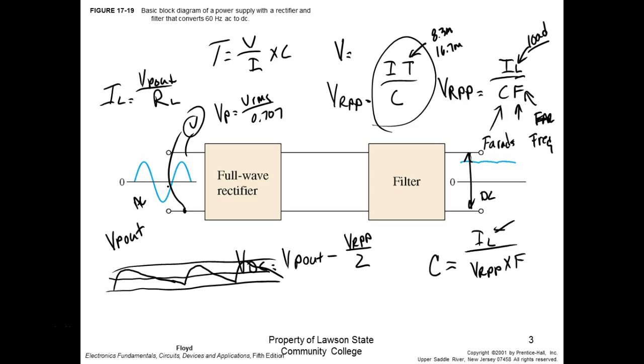Okay. But if they short, it's going to blow a fuse. Hopefully it blows a fuse. If it doesn't blow a fuse, it's going to burn something off. If it opens in a half wave rectifier, then your output goes to 0. Right? You understand? If it opens in a full wave rectifier, then you turn a full wave into a what? Half wave. Which means your ripple voltage is going to go up because the capacitor's got to run the load for 16.7 or about 17 milliseconds now, right? You understand? So it's going to discharge, which will cause your output to go down lower. It's not going to be much, but it's going to be lower, right?